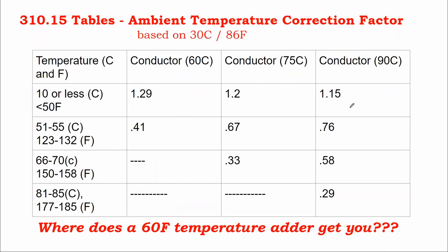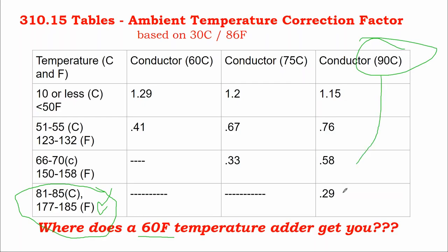Remember, those cables already generate their own heat from the electricity inside them. And so, by the time you get into extreme rooftop temperatures where your cables are 1 inch from the rooftop, you have to be using 90C rated cable just to have something that can be safe up on the rooftop.